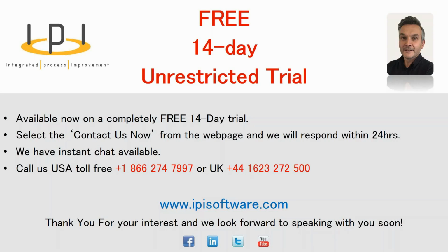The alternate thing is if we come on to control plans, you might not necessarily be wanting to create inspection plans at this stage. Control plans might come first. If that's the case, then Visual CP, Visual Control Plan, will give you a different outlook, a different presentation, and you can link operations to feature numbers there, but also apply other information that you may associate to the AIAG standard with control plans.